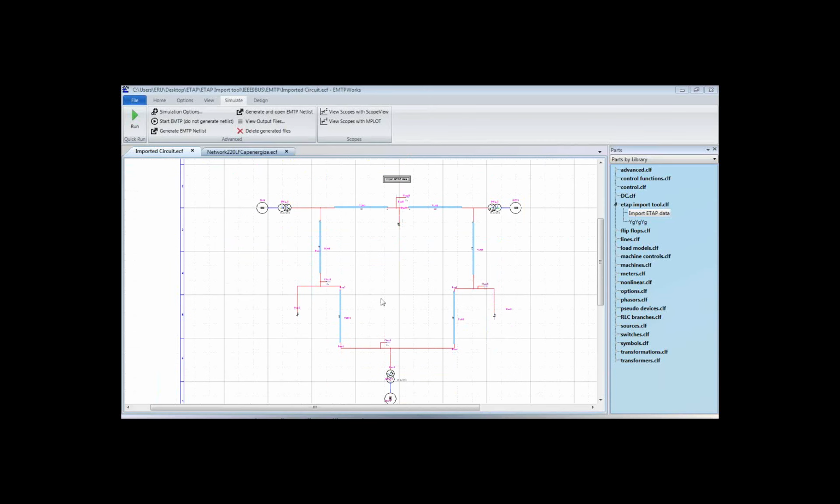And for instance, let's say that we use ETAP for short circuit and for selectivity analysis. But now we want to perform a capacitor bank analysis. We want to check the overvoltage that we'll have on this bus when I'm connecting a large capacitor bank, and we want to make sure that the equipment that are connected to this bus are correctly sized.